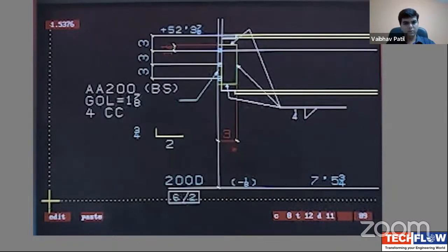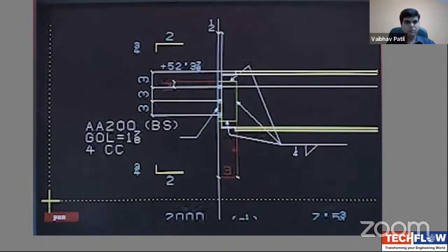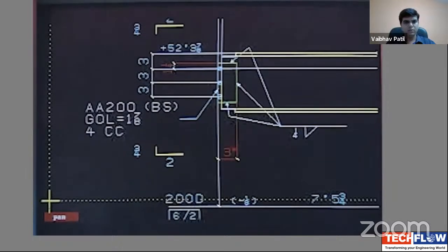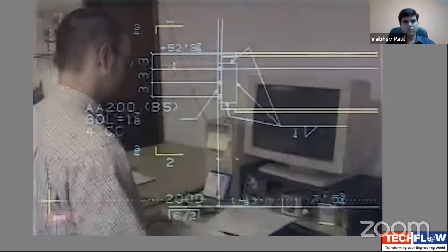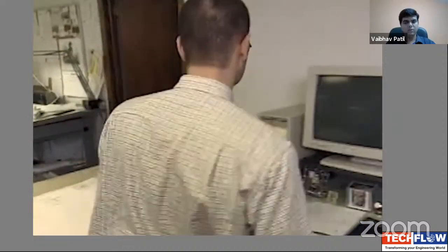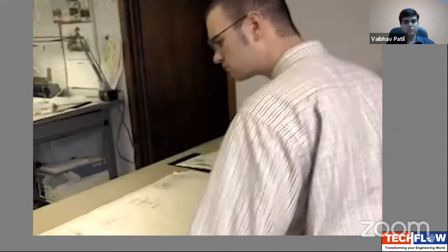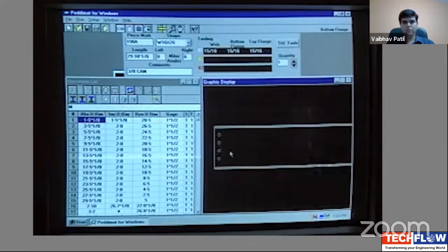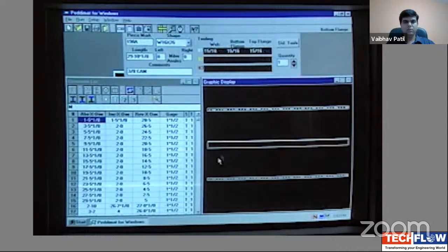To accomplish this process, the detailer must compute the length of the beams and columns, as well as the bolts and raw material to be used. The detailer must also keep track of every hole in the entire structure. If a change is made in a beam connection or in the hole of one column web, it will be up to the detailer to indicate exactly how that change will affect all the holes in those beams.